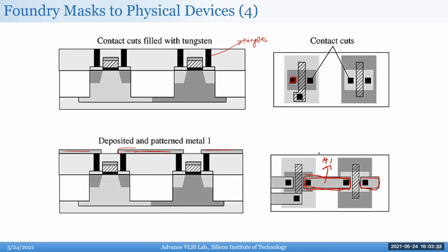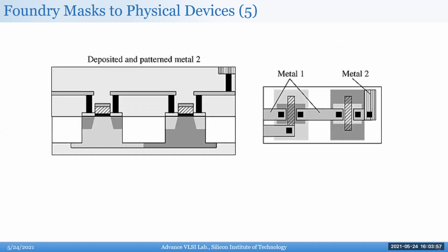And then obviously you have more metal layers. Finer processes now have all the way up to 13, 14, I don't know, maybe 20 metal layers. The first monolithic process we started with just had one metal layer. In fact, there are a lot of processes we work with now which have just 2 or 3 metal layers, because everything adds cost. Like I said, in IC design, everything is cost driven.